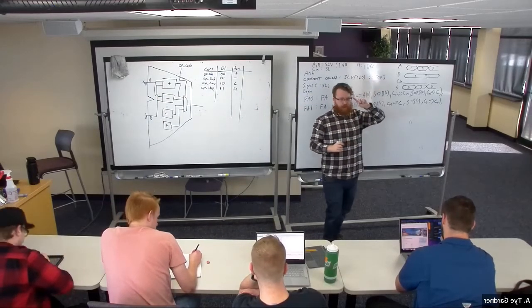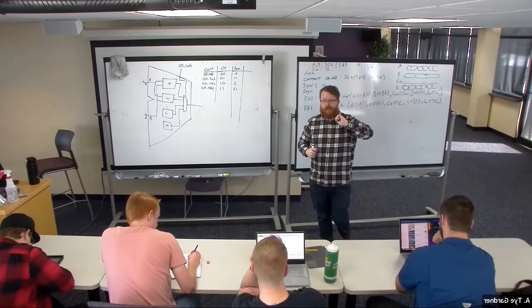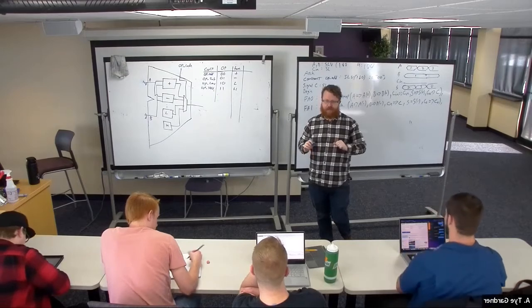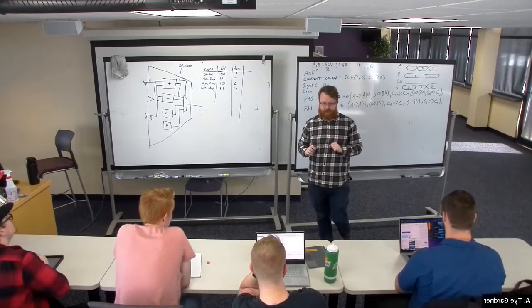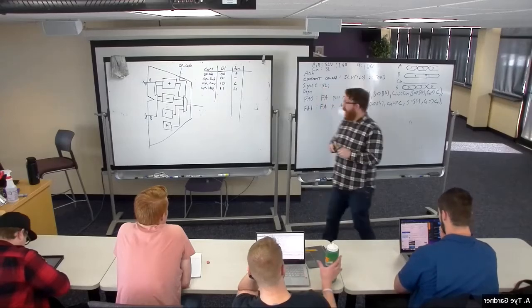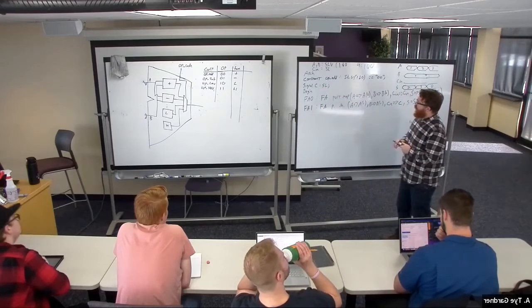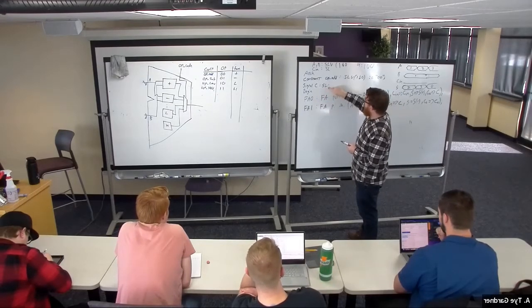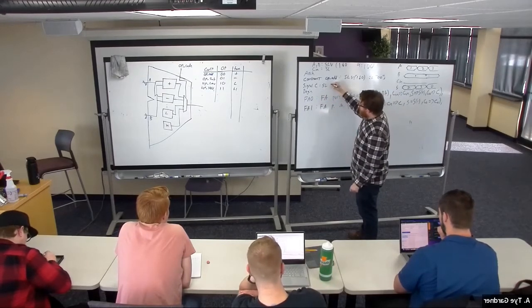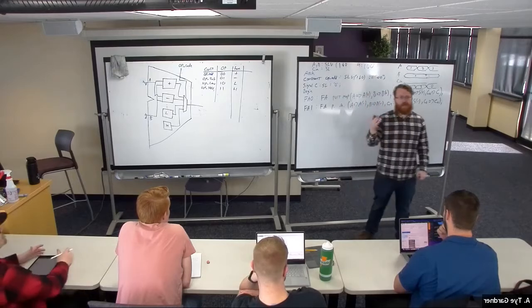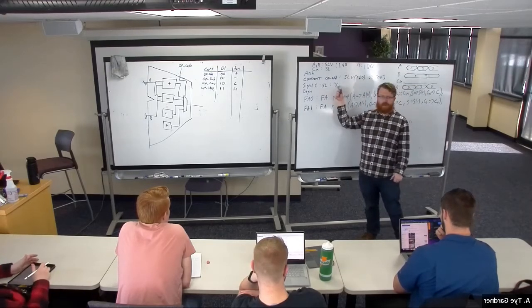One word of warning that is very important to be aware of is this works wonderfully for constants. This does not work very well for signals. And it's easy to get fooled because if I were to do this for a signal here, signal C is standard logic, I'm allowed to type this, 0, 0 is standard logic 0. That's saying I want this signal to start at 0.